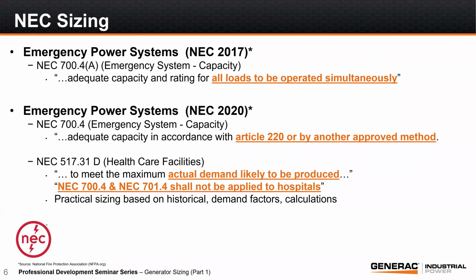By doing this, you'll likely avoid having the generator be so lightly loaded that you run the risk of wet stacking due to oversizing, which of course brings its own set of problems when that happens.